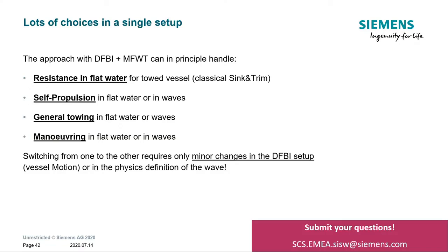We can certainly apply self-propulsion, releasing the advanced degrees of freedom, again either in flat water or in waves. We can apply a general towing, just switching the DFBI motion option, and releasing all degrees of freedom and including some rudder forces. We can also study general maneuvers even in waves. The important point is that switching from one of these applications to another just requires some minor changes in the DFBI setup.